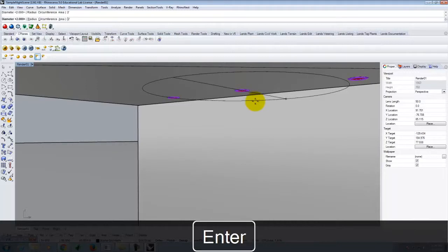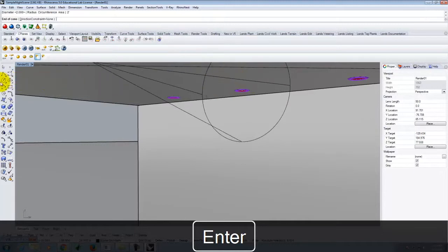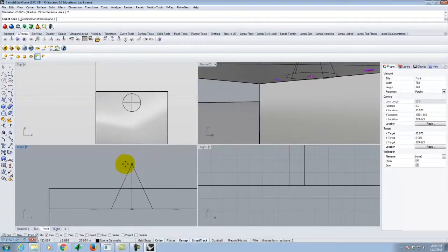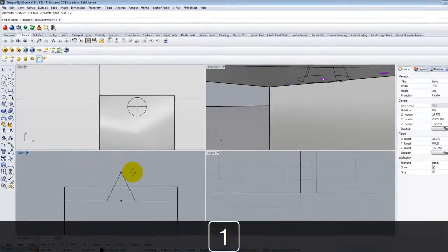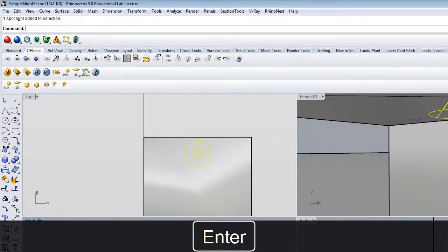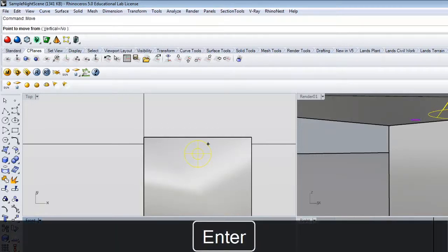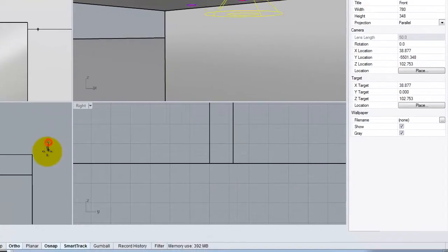Right? And I want the height of this spotlight to be 1 foot. A lot of times it's easier to use the front view to specify 1 foot. Okay? So anything in this ratio, 2 by 1, works pretty well for a can light. Now, in order for this to work, I have to make sure that the origin of the light is below any geometry.